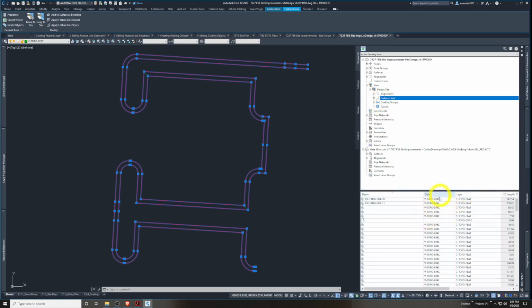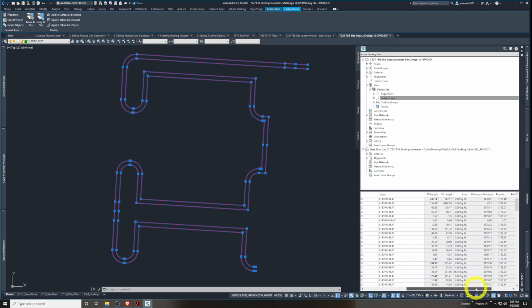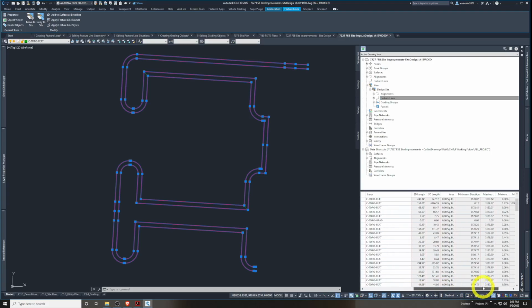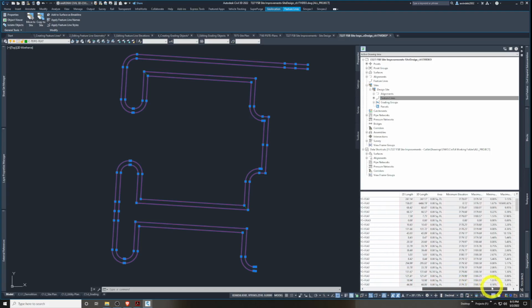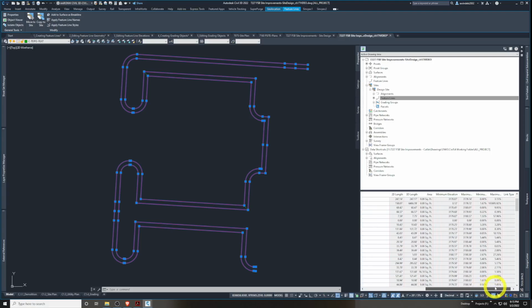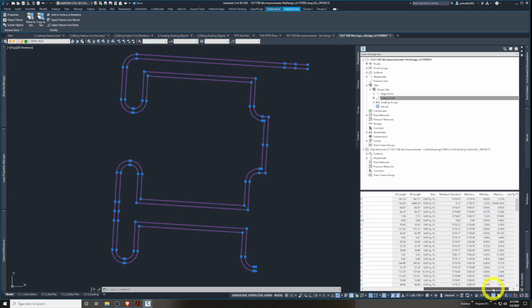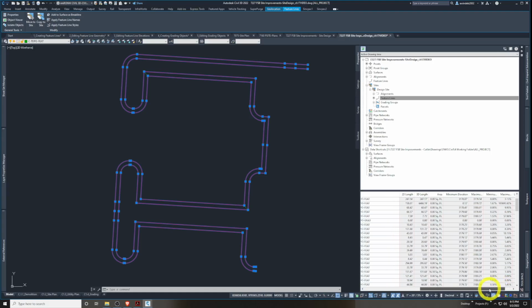They have their own given Civil 3D style, which is an internal one to my company. VTOPO stands for brake line, BRKL. They also populate on a certain layer, and they have all the fixings of an alignment profile. They cannot have vertical curves though. So they're a little different in profile that way. They can't have a vertical curve in the vertical. They can only tessellate, or make little miniature straight line increments to simulate that curve. So that's one of the few things they're limited on.